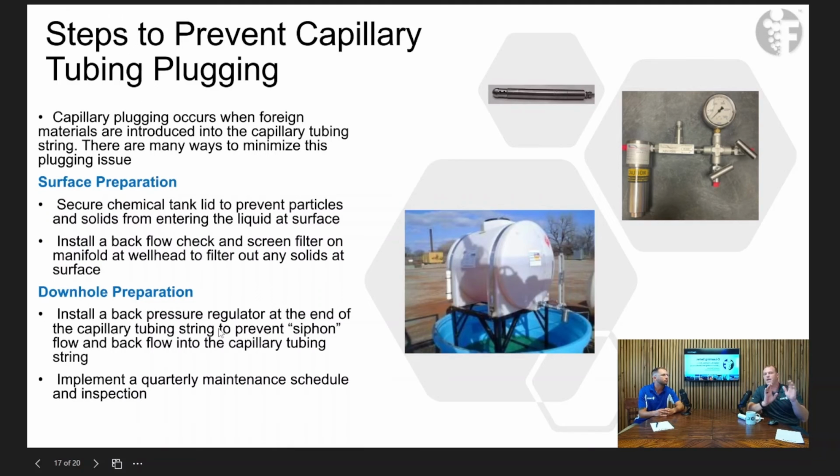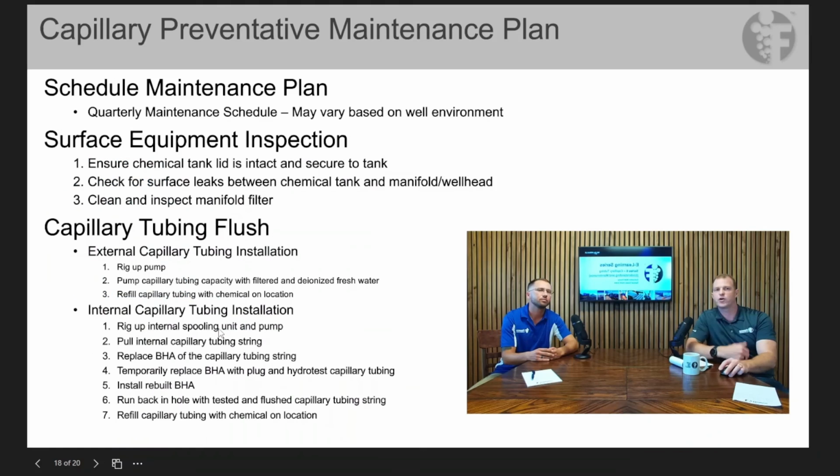And so you're talking about maintaining that cap tubing once it's down hole, right? And your big fear with cap tubing is it plugging up? Yep. And that typically happens, going back to the tank. If anything's going to happen, it's going to come from that tank. And so making sure your lids are on.